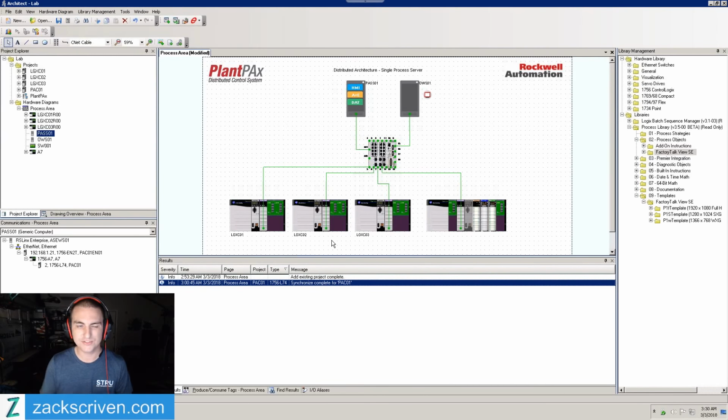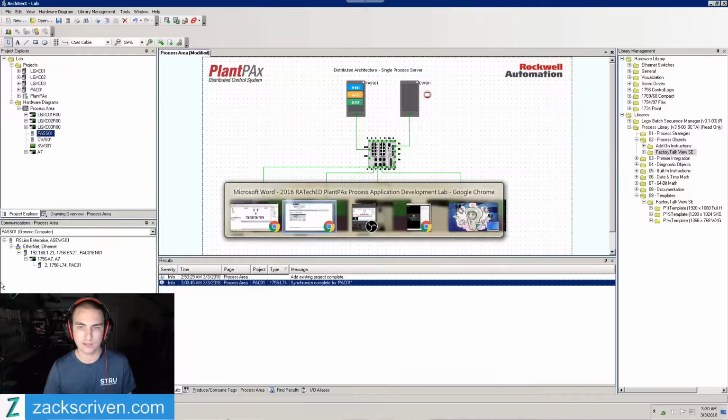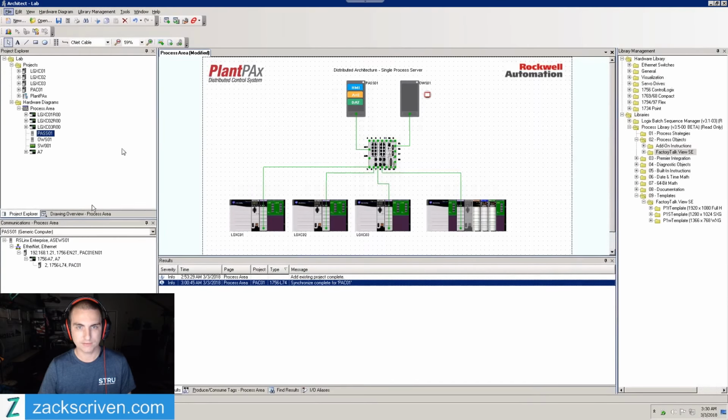So basically that's just linking the shortcut. You guys are familiar with FactoryTalk View SE. It's kind of like the access path for where it's getting that data. It's kind of like a shortcut, and then you use that for your tagging. So just by dragging and dropping it there, you see how that was really easy to configure that shortcut. I think that's really cool. We'll save. Okay.